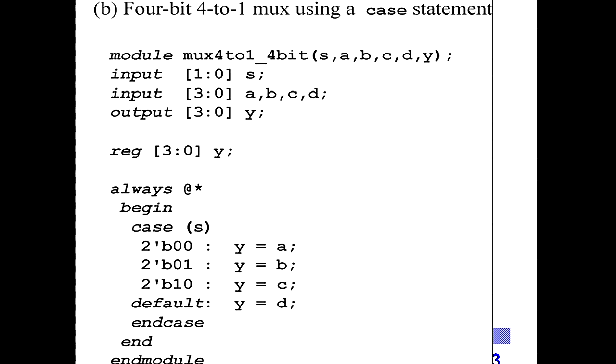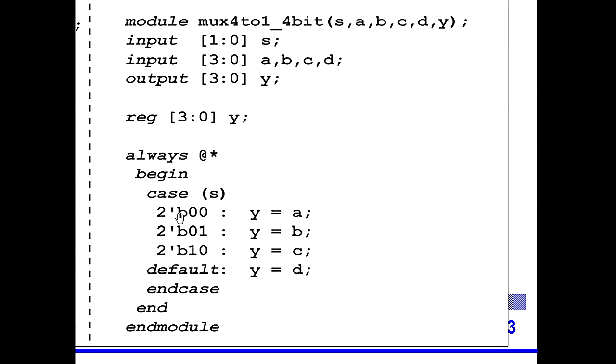So when you go into Quartus, you can look up the syntax for these things. I know it's a bit overwhelming looking at it in these examples, but you can then say I want a multiplexer, and it gives you a template set of syntax you can then edit in the editor. So that's what I'd recommend you do, because you've got to remember the end case, the default, and putting in the switch inside the brackets, all that stuff.